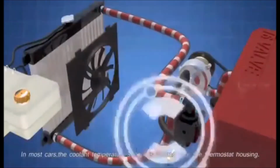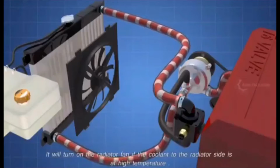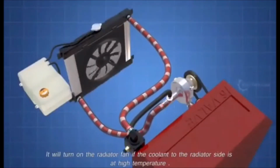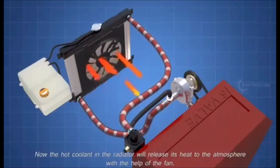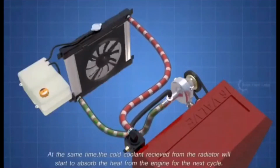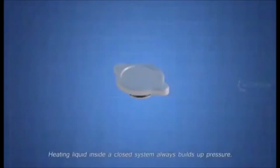The coolant temperature sensor is located near the thermostat housing. It will turn on the radiator fan if the coolant to the radiator side is at high temperature. Now, the hot coolant in the radiator will release its heat to the atmosphere with the help of the fan. At the same time, the cold coolant received from the radiator will start to absorb the heat from the engine for the next cycle.